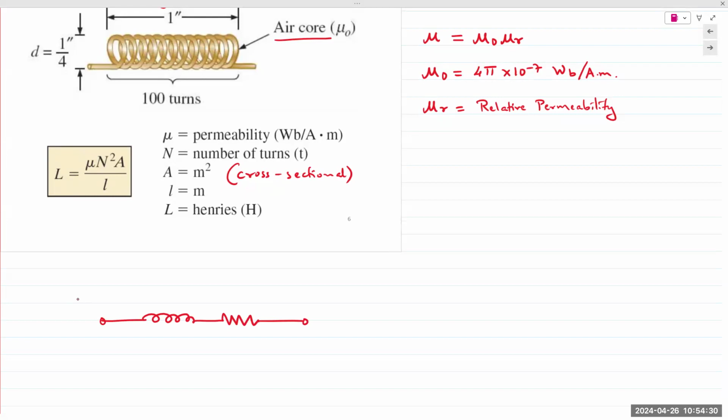So physically it's the exact same component. We cannot separate out the resistance from that inductance. But electrically, if you're trying to perform a calculation or a simulation, we need to have 2 separate components. So we represent it as an inductor in series with a resistor inside a box.